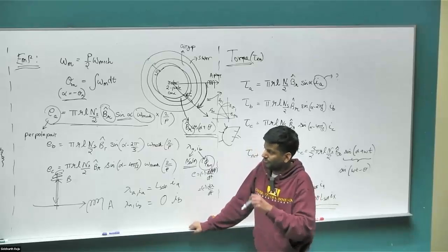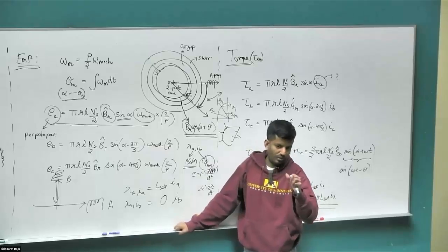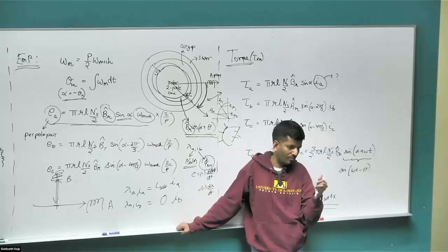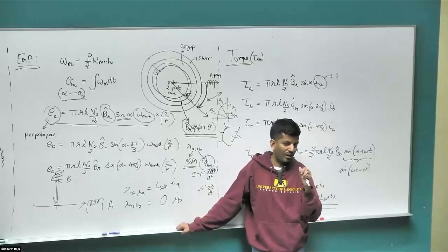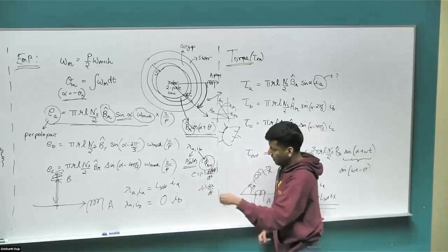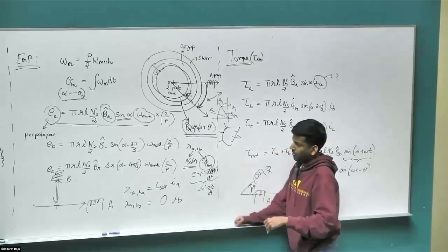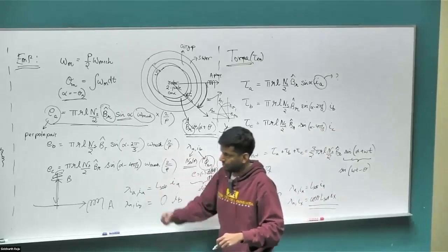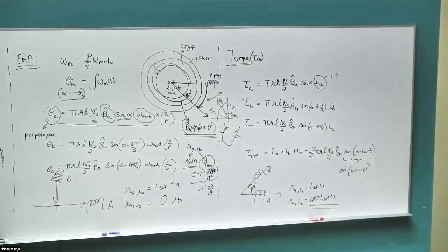So this is because of the rotor rotating. When the rotor rotates, there is going to be a changing magnetic field in the air gap because the rotor magnetic field is varying. That varying magnetic field is going to link with the stator coil, which is then going to create an EMF, which is given by this term. So we have this EMF term come into the picture, and that we are going to capture with the voltage source.